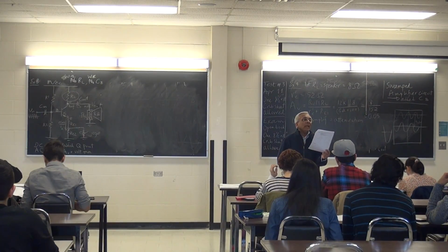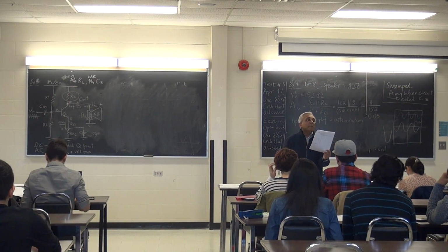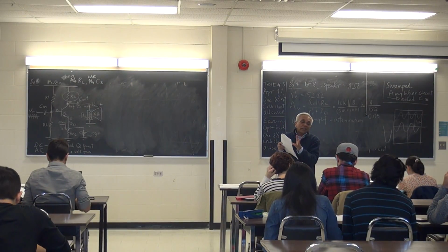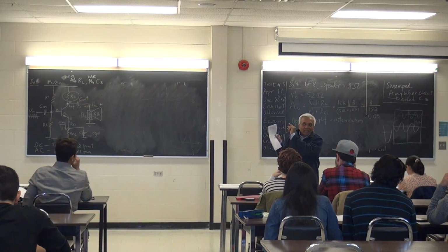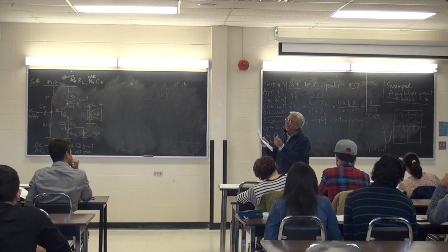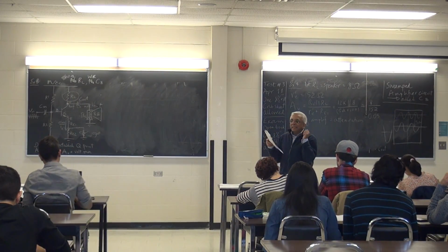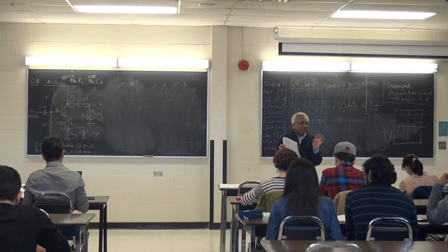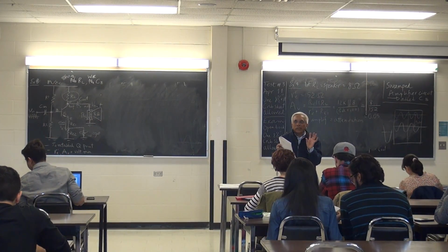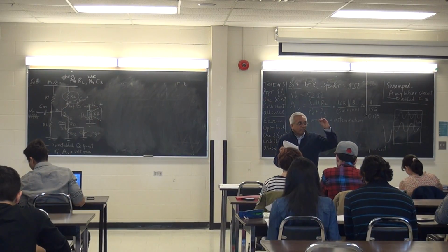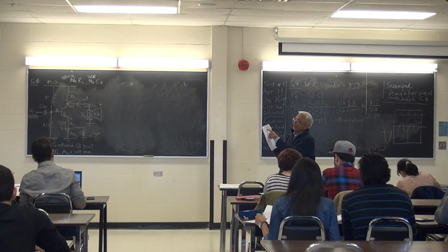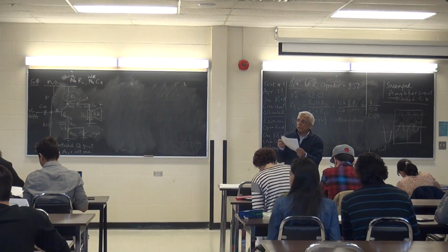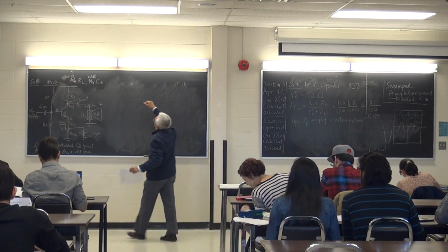With these amplifiers, the math for this circuit, or the way to analyze an amplifier circuit, is to have a couple of assumptions or rules of thumb or behaviors of the circuit. So right at the top of the page, what does it say? For AC analysis, the capacitors C1, C2, C3 are what? Shorted, which means closed switch, right? Write down closed switch beside the word short.